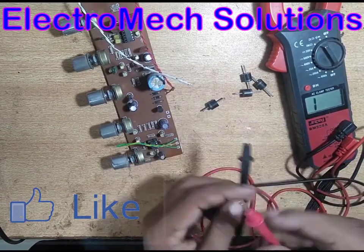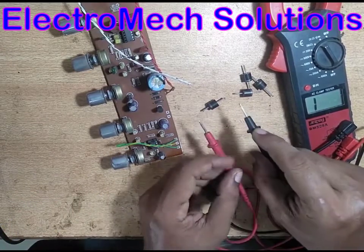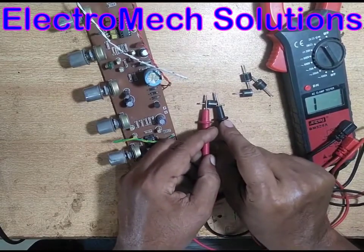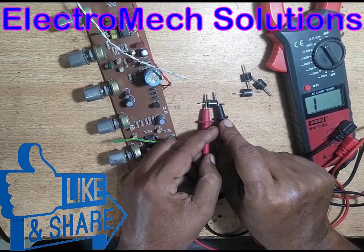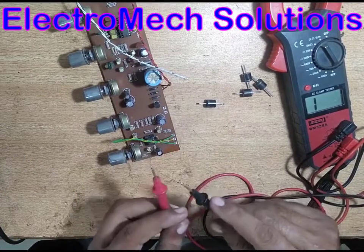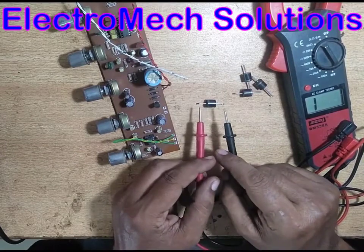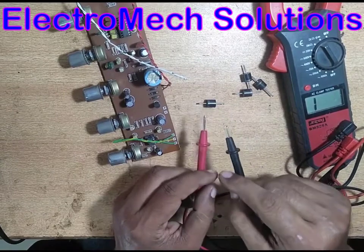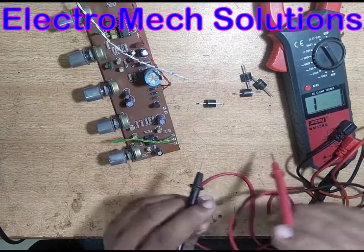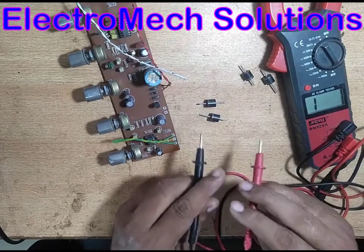When we connect in the reverse bias, it will tell us the off position. The circuit is off, the path is off. As you can see, there is no change. One means infinity. So in this position, you can say it behaves like a switch. In one direction it is closed, and in the opposite direction it will behave as an open switch or open circuit. So every diode you can check with the same method.